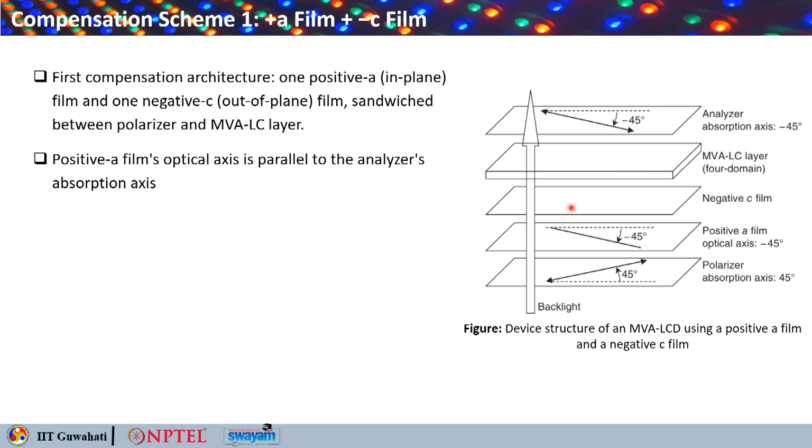Here the objective of the design is that we want to choose the thickness, and hence the phase retardation, of each film such that at 0 volt the observer looking in from an oblique bisector viewing direction still sees a fully absorbed black state, exactly as they would have seen it on axis.